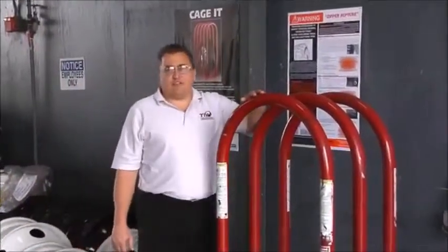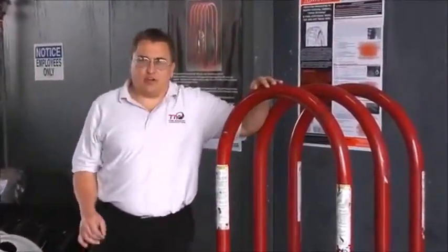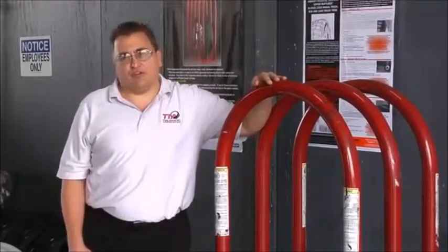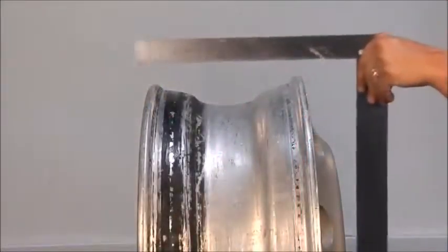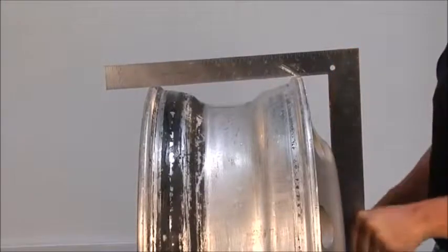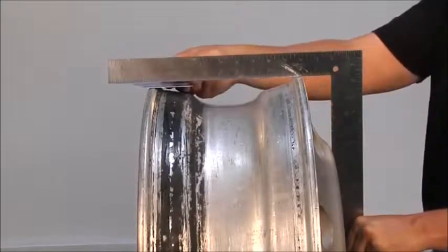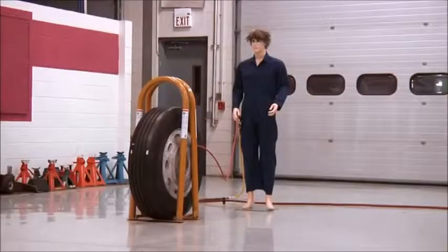A restraining device is designed to absorb the energy and prevent a tire and wheel assembly from becoming a projectile during inflation. For example, if a disc wheel is damaged by excessive heat, the rim diameter on one side becomes smaller than the other. In this controlled test, a tubeless truck tire is inflated on a heat-damaged wheel. When the tire and wheel assembly is properly positioned within a restraining device and the technician is standing outside the trajectory, there is minimal risk for injury when the tire separates from the wheel.